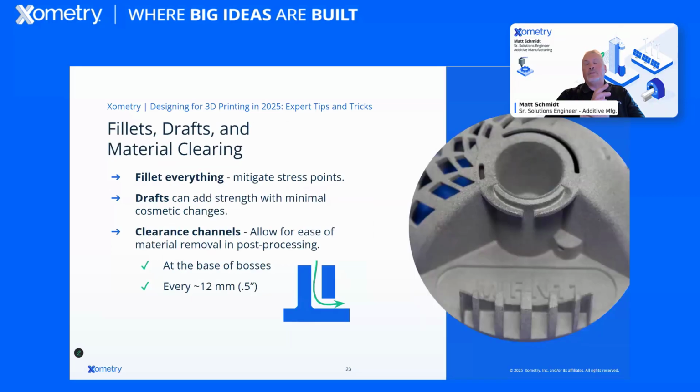Yeah, increasingly important to consider support structures when it comes to metals and considering part orientation when it comes to your DFAM approach, your design for additive manufacturing approach, which will help you look at support structures, how they can be removed, where they're going to be contained, and if you can get away with utilizing them or not utilizing them. But we'll talk about a tool coming up here that can help eliminate some of that for you.